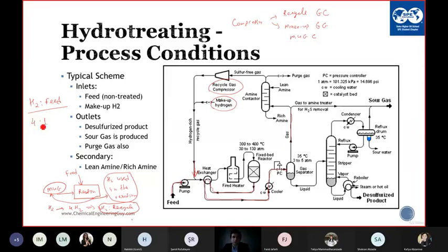The more hydrogen you have, the bigger the reactor you need, but the better the process. That's why you have to look at the pros and cons, where you have the lower cost and at which point it adds costs, and then you stop at this ratio. For instance, you can go to 4, 5, 6, but when you go to 10, you will see that you need a much bigger reactor. That's why you don't go there.